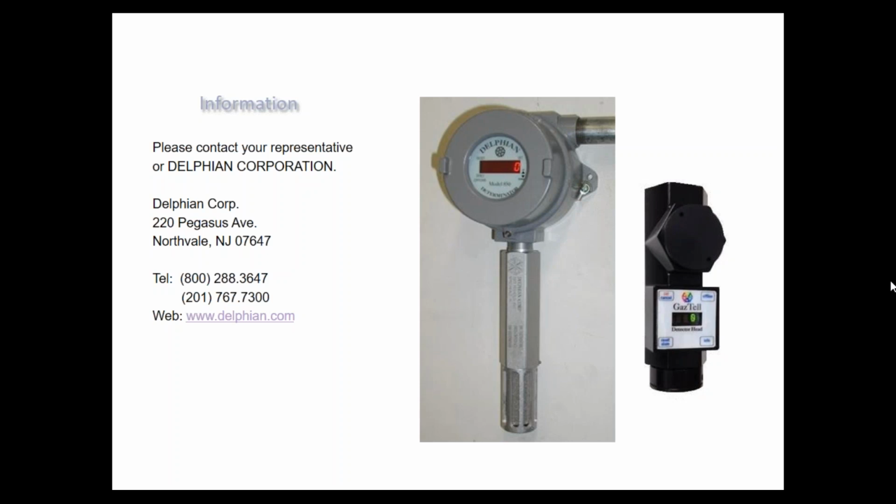Number two, the only thing open path can do is say, do I see gas or don't I see gas? Its accuracy is nil. If you have a very high gas leak, let's say you have an open path looking at a 300 foot span, and a gas leak right in the middle that's 1 foot wide and it's a big leak, that open path is going to say you have an average of 10% LEL over the 300 feet.